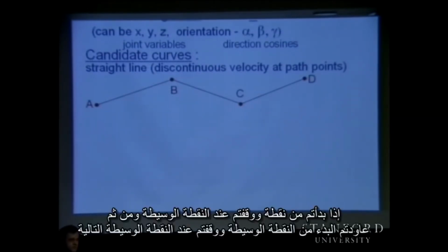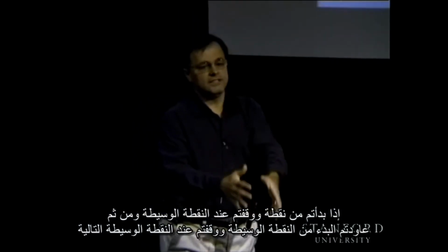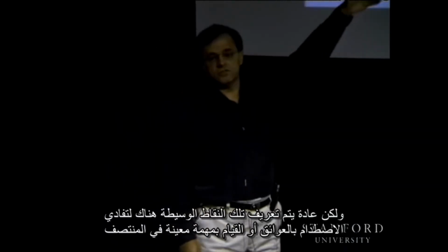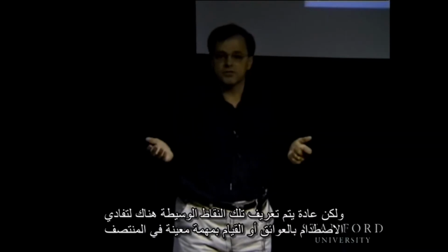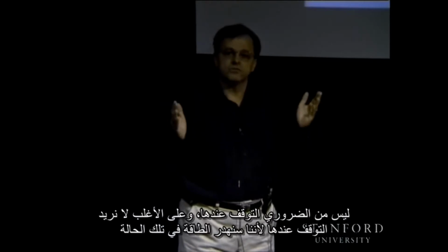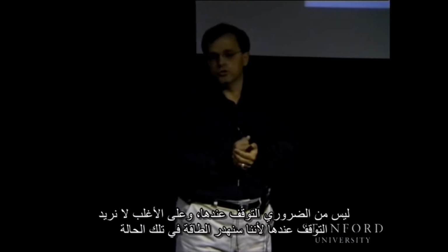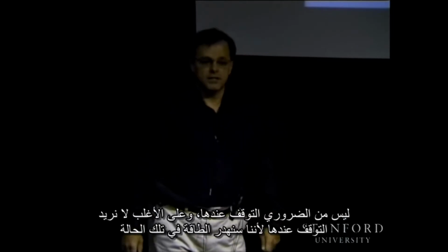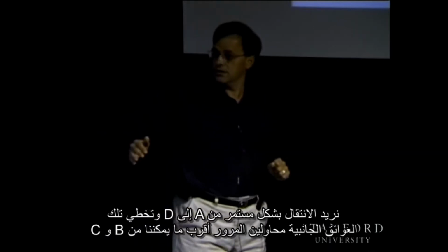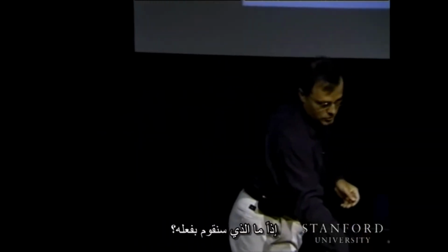If you're starting and stopping at each intermediate point, that's fine. But usually those intermediate points are introduced so that we don't collide with obstacles or so we can achieve certain tasks in the middle. It's not necessary to stop at them, and we probably don't want to, because we're wasting energy. So we want to go continuously from A to D, avoiding the obstacles on the side, going as close as possible to B and C. That's usually the goal.